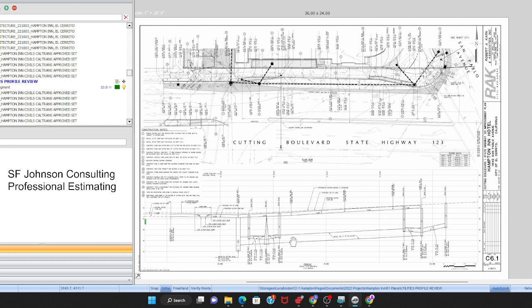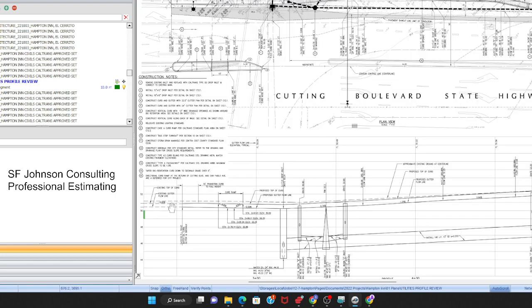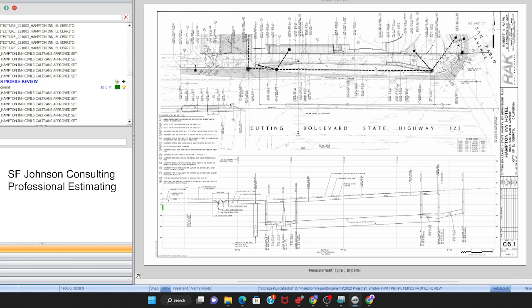Okay, so when you are doing excavation, you need a profile view. Don't try to drive yourself crazy. Okay. Sometimes a set of plans will give you how many cubic yards to get it right, which is great. Okay, so we do the main excavation, and then once we get it back to ground, then we fine grade it, right? And then we go in, and now we're going to do the work to install foundations and stuff like that.